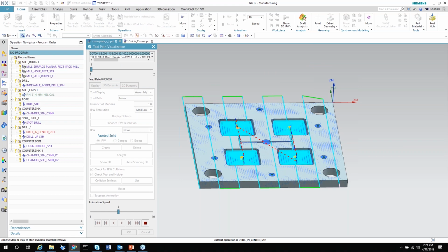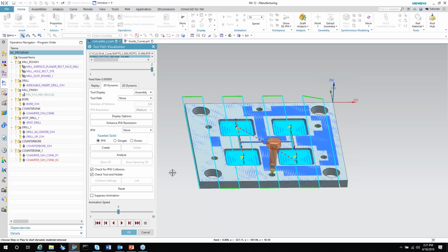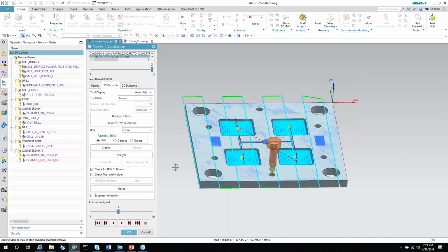But you can see I've programmed this part in just a few minutes, and what you can do with this is you can change that, go into the machining knowledge editor and change the way that it processes these features. So if you wanted to keep your carousel of tools for the first 25 tools exactly always the same tools. For an example, I had a customer that's a stamping facility that does plate work like this constantly.